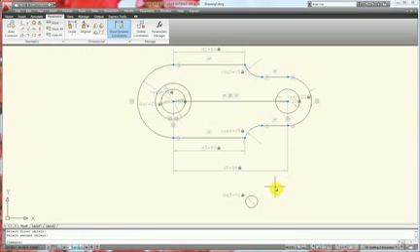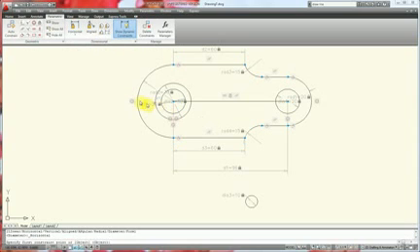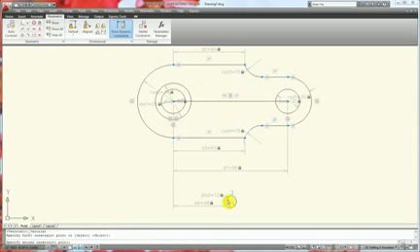And now this little circle needs to be placed at a location up here. So we're going to use a combination of horizontal and vertical dimension constraints. So I'm going to use a horizontal constraint and constrain it from this center point to its center point of 48. And then we use a vertical constraint and constrain it from this line to the center point of the circle of 0. Notice how it brought it back up to that line, and also it's in line with this guy.